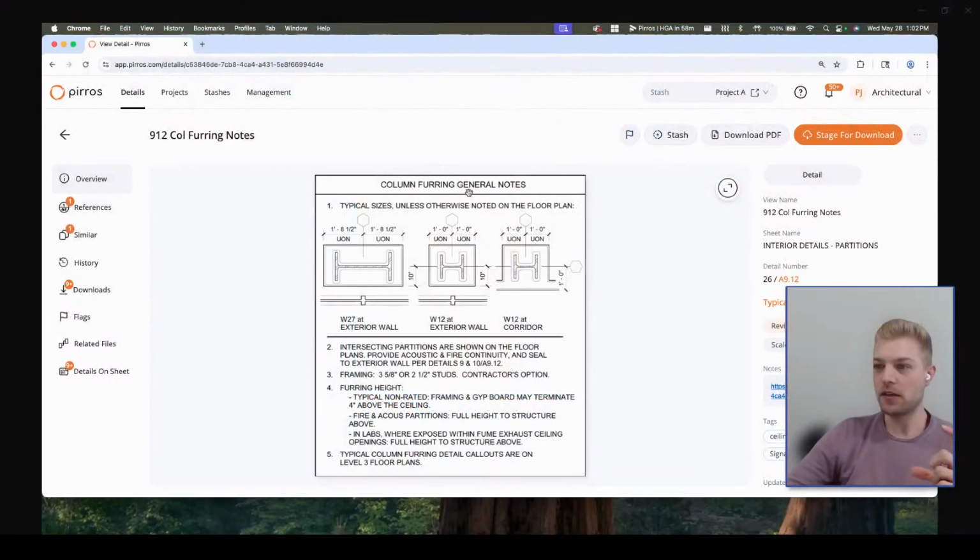JR asks, what gets uploaded to the cloud? The PDFs only, or also the Revit models? It's the PDF. So every detail that you see here, we're seeing the .pdf file of the detail. And then on the back end, there's this exact detail. There's a .rbt file with just this drafting view or just that detail view. So you can quickly download into a project.